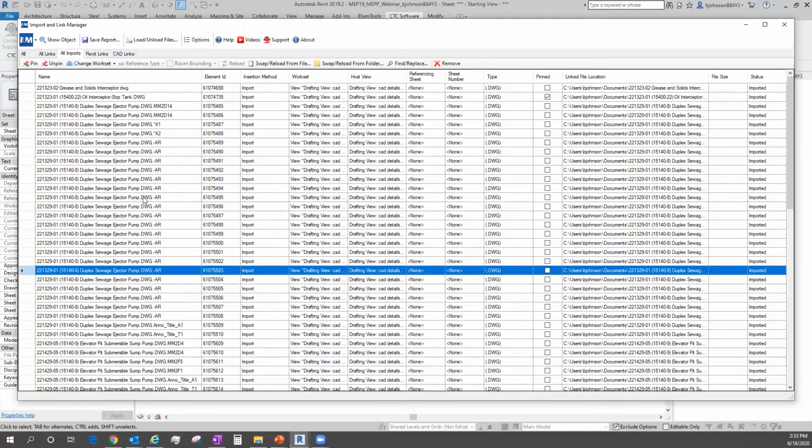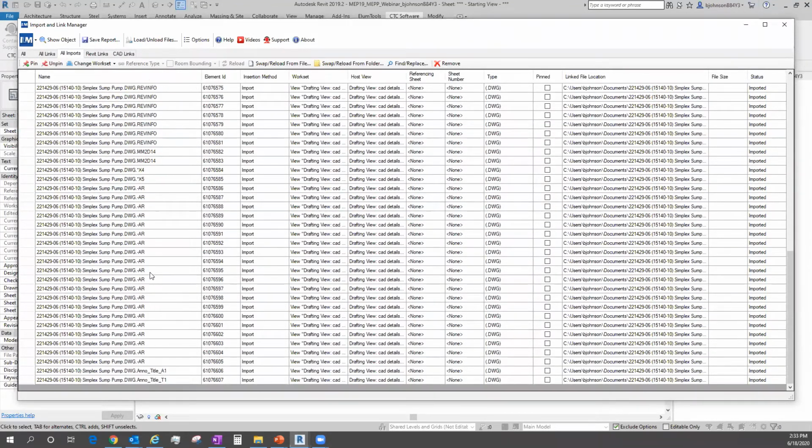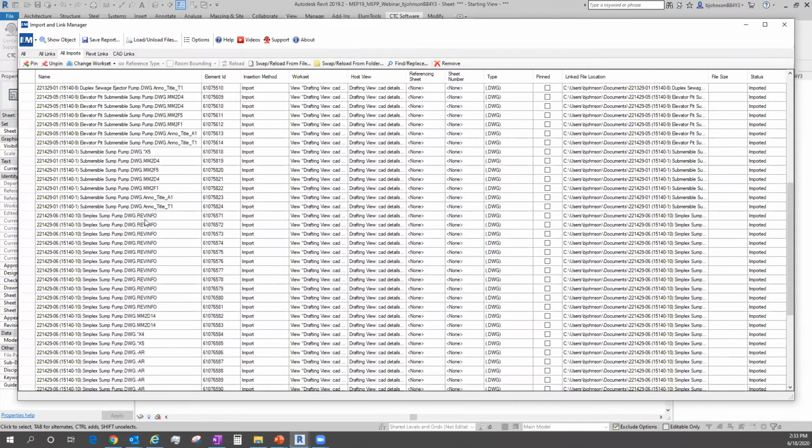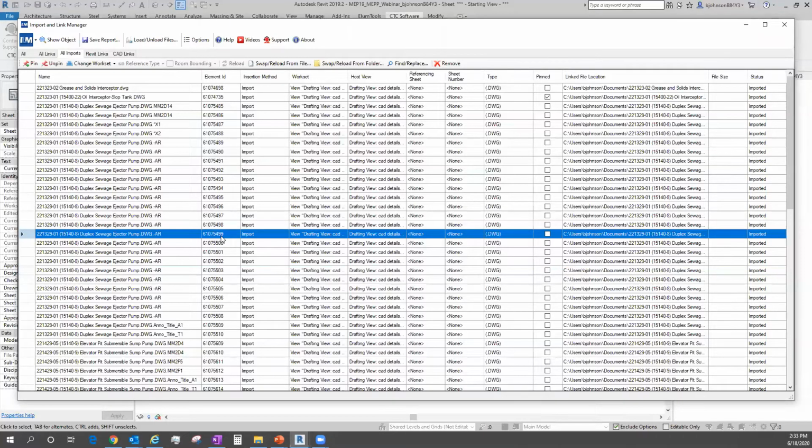So based on our types here, being able to see what's in the Revit model, I can definitely tell there's a bunch of these that have been exploded. What would be the easiest way to find out the whodunit? In this case, a lot of people, especially just plain Jane Revit users, not the CAD managers, don't really know that once you find an object inside of Revit, if you can find the element ID on it and go select it, you should also be able to see who actually did whatever the last function was.